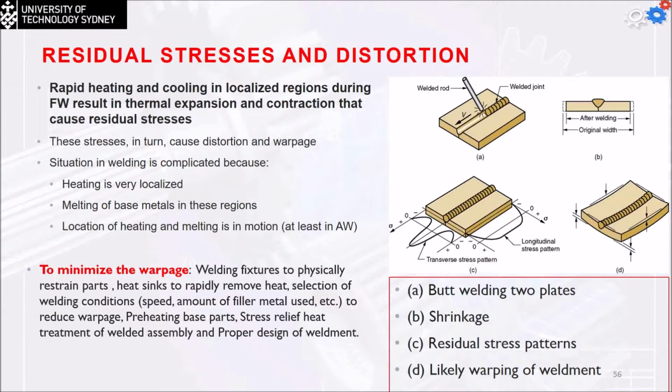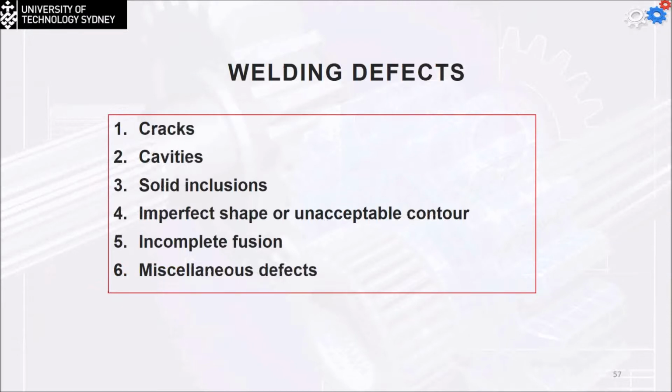So first, the welding cracks. These are cracks we may have either on the workpiece or in the welding area. Welding cracks are fracture-type interruptions either in the weld or in the base metal adjacent to the weld area. Both are heated to a high temperature, then they contract, and that's why we have the fracture within. It's a serious defect because it creates a discontinuity in the metal that significantly